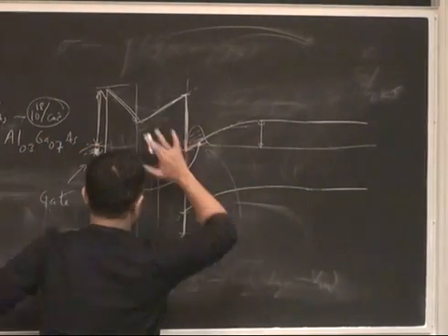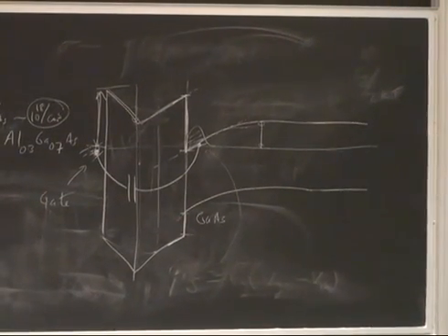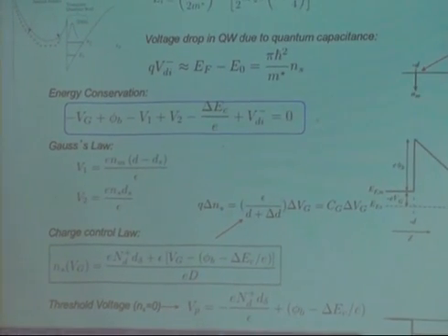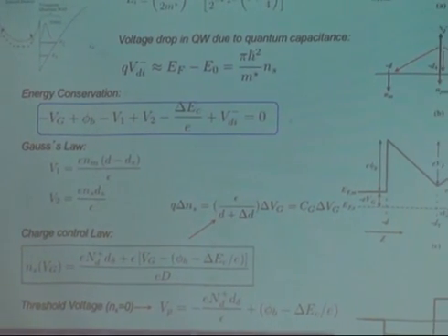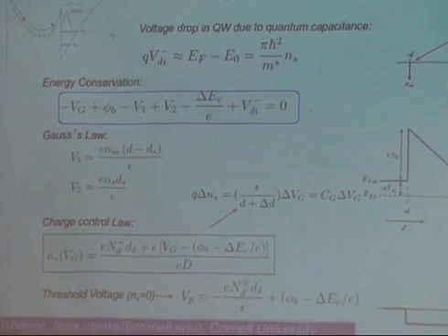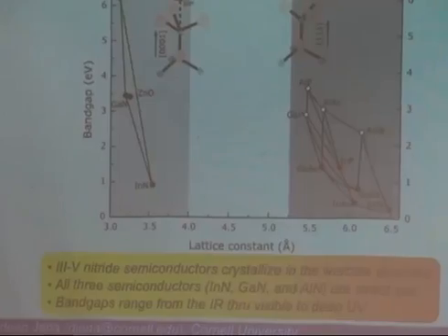From that relationship, you can find the carrier density dependence on the gate voltage. You can relate it directly, and it's going to be an effective capacitance times the gate voltage. Then you can find at what gate voltage this effectively goes to 0, and that is your threshold voltage, which is standard stuff. Nothing very fancy in that.